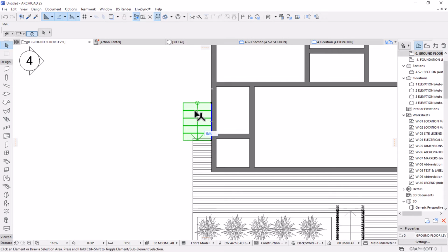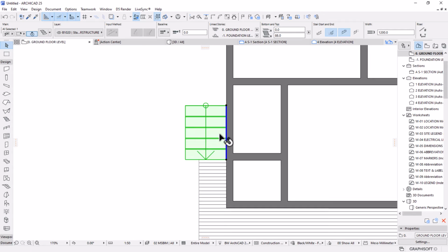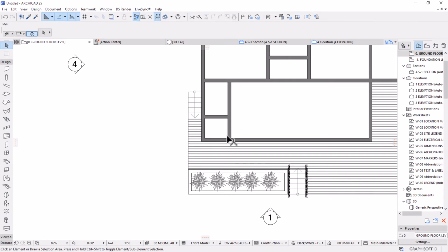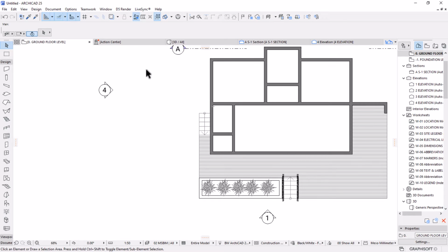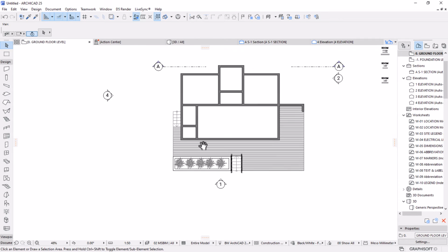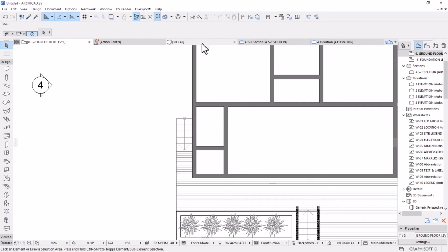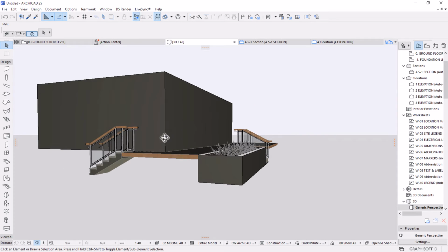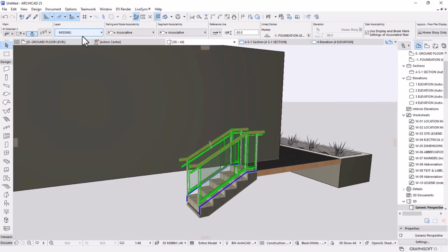Okay, pretty interesting. So I'm going to select the staircase and then move it to the point, Control D. Let's say Control D and then move it back there. I think the width is supposed to be 800, something like that, because it's just for accessing the outside toilet, more especially if you are coming from down or from the ground level. But if you're coming on the deck here, you can just go and then access it. Good, pretty stuff. Yeah, I don't know why the railings were not placed. You can check in 3D and confirm that, oh, they are there, they are placed. But it's just for us to make sure the layers are right.